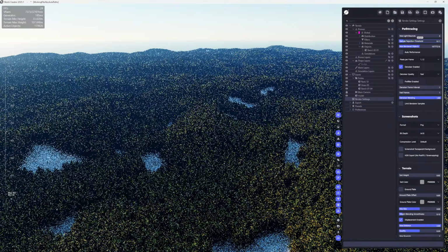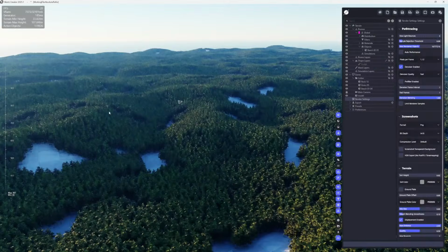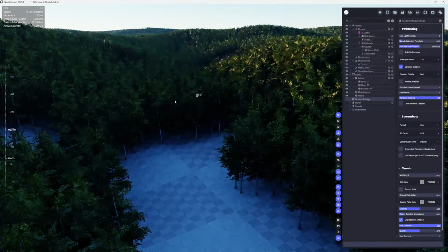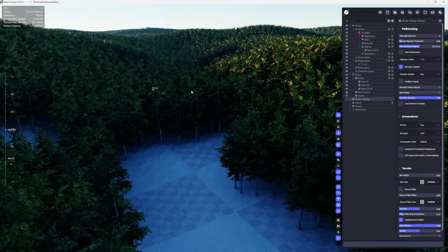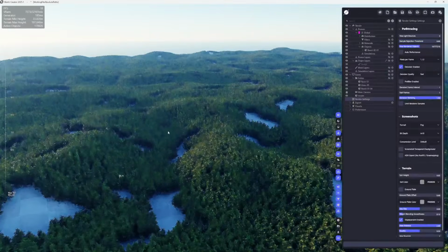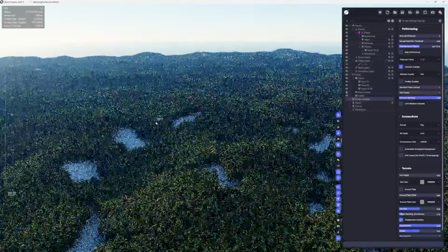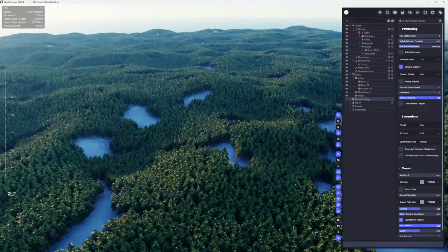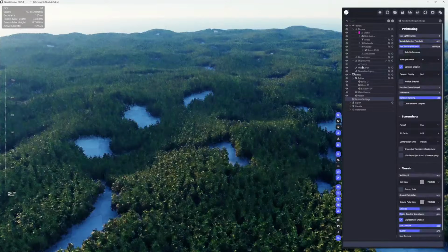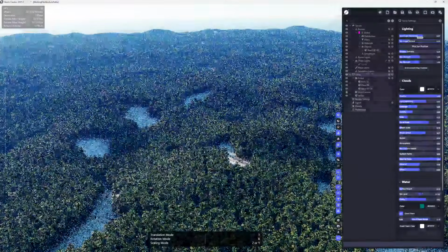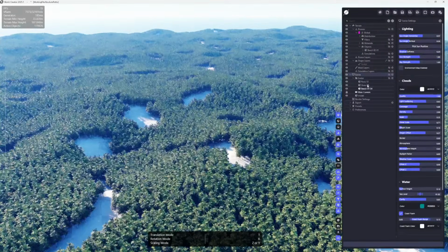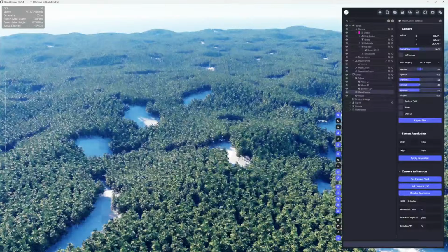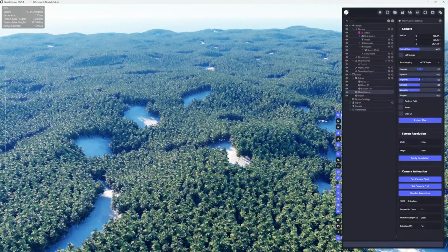Remove that sample rejection threshold a little bit. You're lighting up the entire scene. It looks way better in lighting, okay? In this case, it's too dense, of course. So you can play with these values to do it a little bit better here. So I would say for now, if you're aiming for videos or screenshots, something like that, then play with the sample rejection values. Play a little bit with the sun settings here, and also play with the camera. Where is it? Here we go. With the camera brightness and contrast values, and with the exposure values specifically, to lighten up your scene.